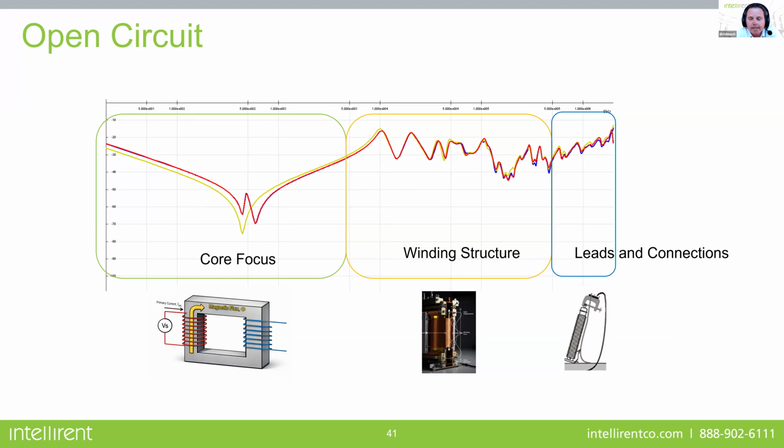So you can clearly see, even in this one, the open circuit on the low side, you look at the core, and notice how there's one phase that's just like a V. That will be your middle phase, which has just one resonance point. Your two outer phases, your A and your C, will have two resonance points in that core frequency range.